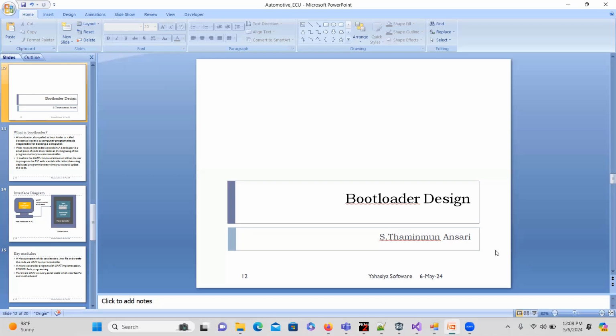Upon receiving it, you will have a program which can work with the program memory. That means for flashing, you have to access the flash memory, so you have to write a program. That program will take care of receiving the executable from the external world and flashing it to the microcontroller. In this way, people can renew the software.